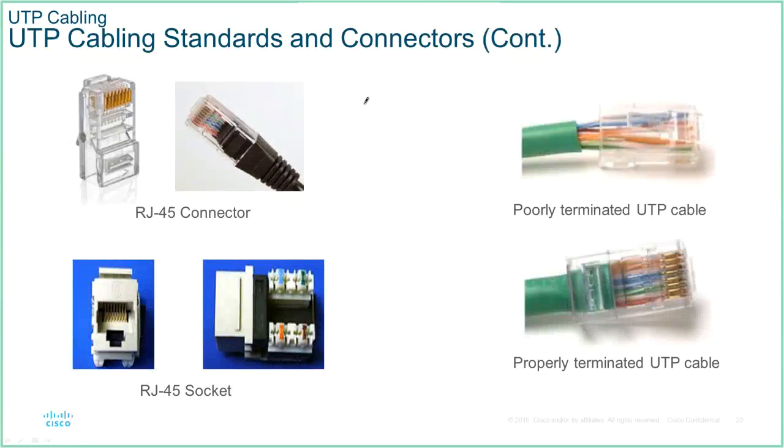Using my mouse, you have the wire there which is made up of all these individual strands, and then when you crimp these together, you actually push a V shape into the wire, and you make connections next to each other with the individual strands.